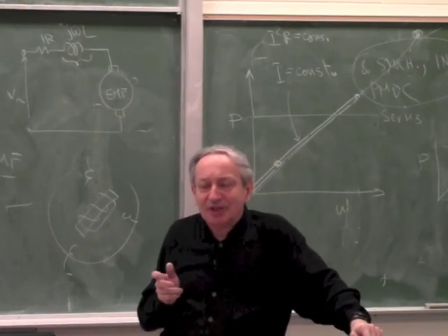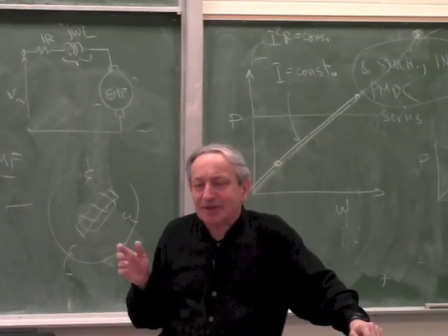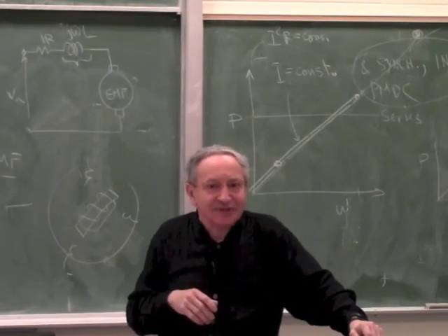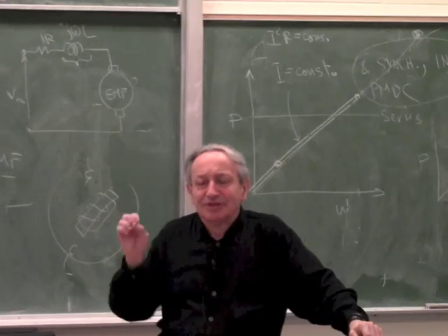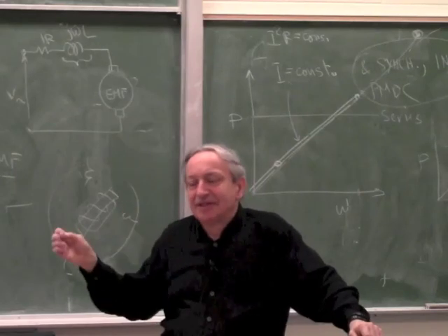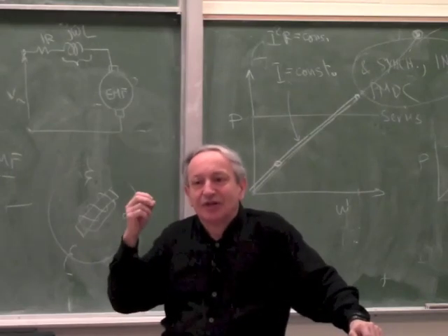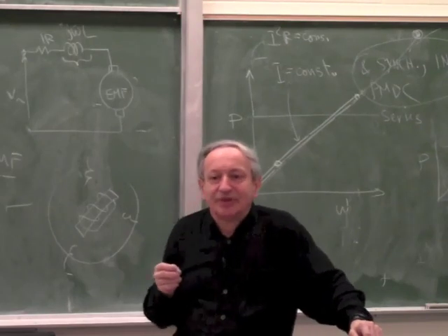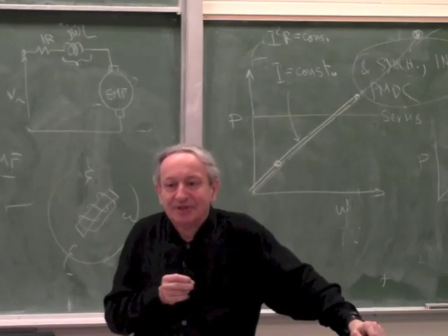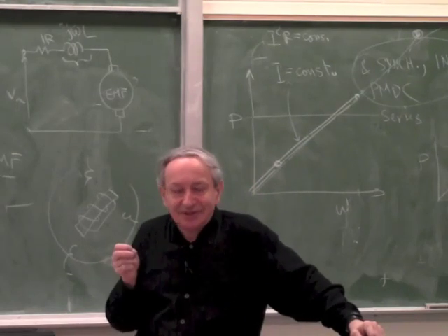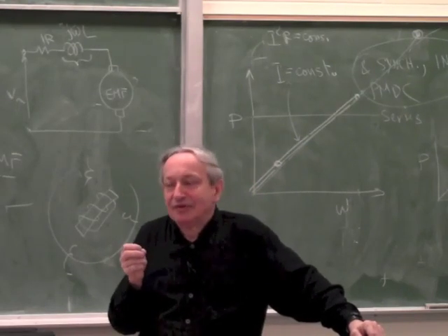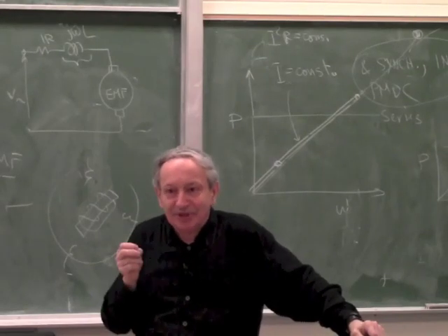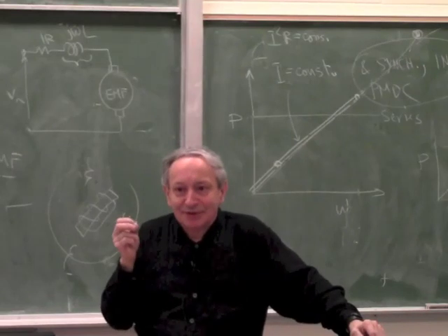The bearings are not a big issue. You can use ceramic bearings, which Tesla uses, and you basically get infinite life. So the real issue becomes noise. It makes a whine. 60 Hertz is very low, not an annoying noise. But if you run a motor at 60,000 RPM, which means 1,000 Hertz, you'll get a very annoying whine. Like if you go to a dentist, the dentist drill is 200,000 RPM, and nobody seems to like that noise.